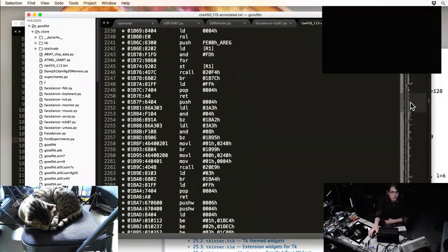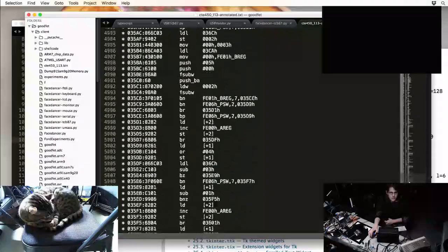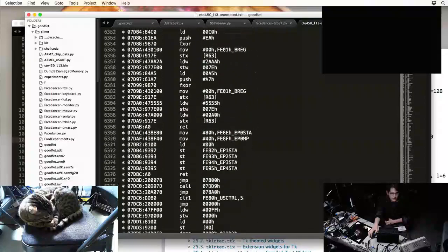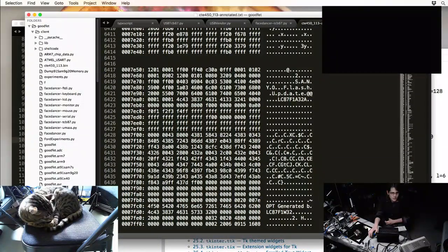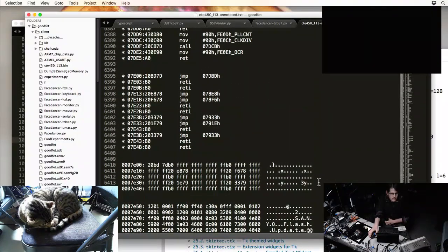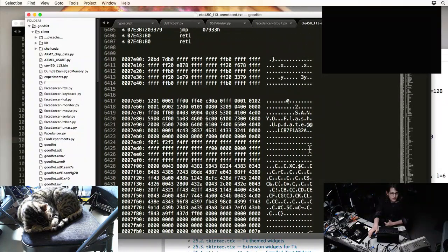I can do just a quick preview. This file has the entire disassembled ROM. I think this was 16 kilobytes, which you can tell based on the data sheet and based on how much of the memory space is being used. And I think this was pretty full. There are also some larger divisions here. For example, this version of the firmware I think includes a bootloader, whereas the 1.16 version that I've looked into much closer doesn't really include a bootloader, and it's a mask ROM version.